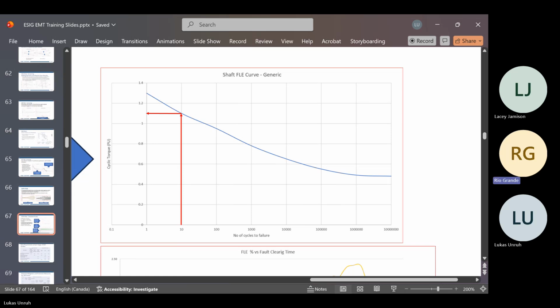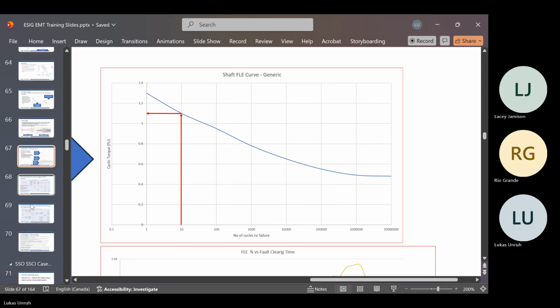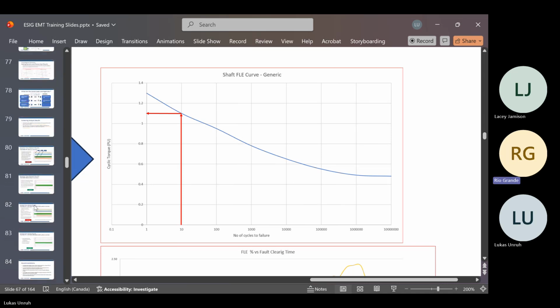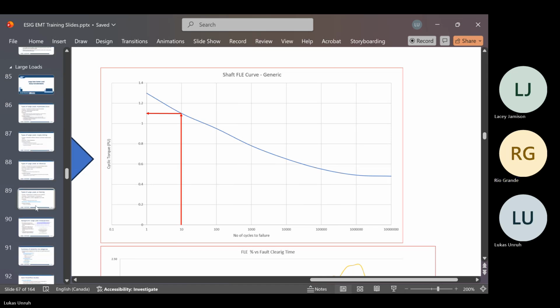This is just a forced oscillation that they're pushing out onto the system by nature of the software process. It doesn't really depend on the damping of the system. It's not really a damping problem. It's going to push out this power regardless of what the damping is. And if we end up in a certain network configuration where a lot of that power is being supplied such that the power variations are visible to the synchronous machine, then we can have torque impacts, shaft impacts.